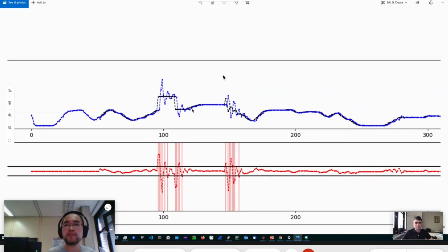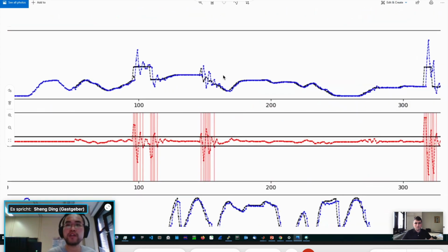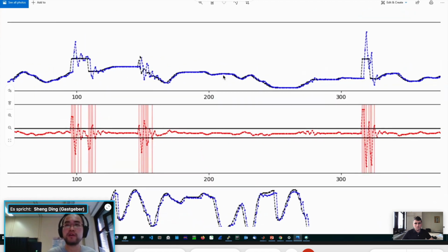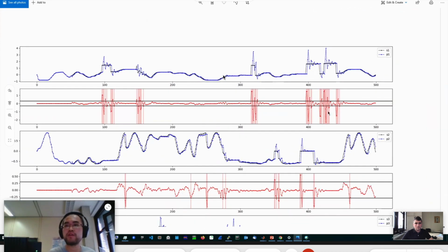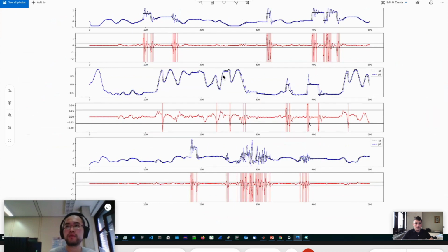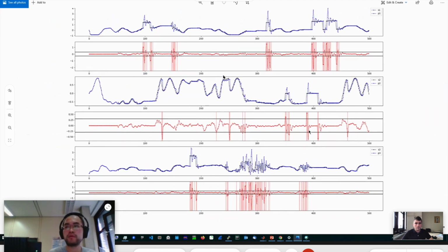Yeah, for example, in the first sensor signal, we have injected an offset at around 10 seconds and a small noise around 14 seconds, and all of the errors are detected. Okay, and on this protocol we can basically see the detection process, and now it is very transparent, so we can see when we injected the errors and when they were detected.